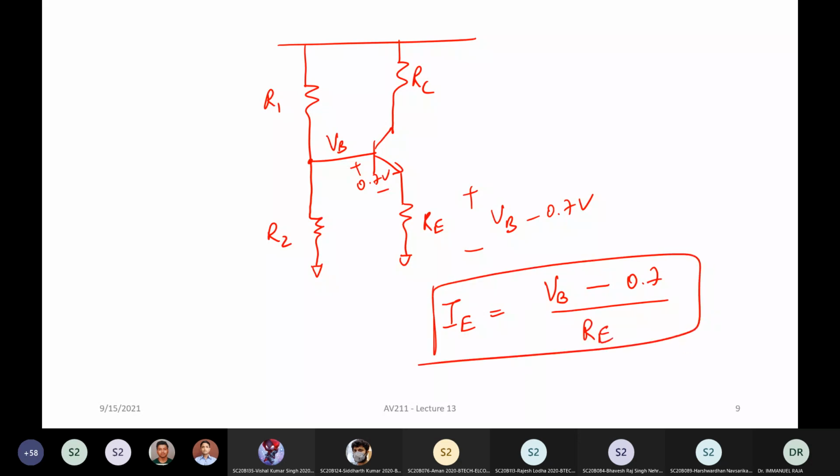The most important thing is, as you pointed out, R1, R2 variation will be there, RE variation will also be there. But for example, if you expected 1 milliamp, you will probably end up with plus or minus 10%, which is still okay. If you allowed the BJT to do whatever it wanted to do, then you'll have a much worse variation. Does it answer your question?